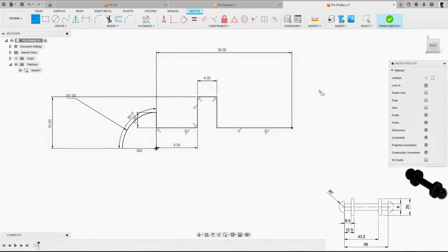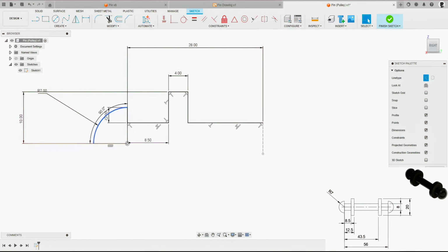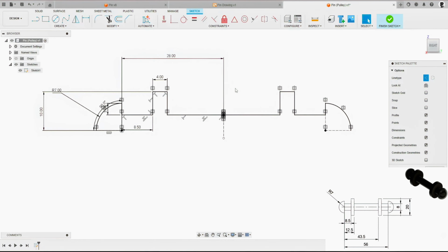Okay. Next, I'm going to use the line tool. I'm drawing a construction line down. And so the idea here, I'm sure you recognize already, is to mirror this across. And then we'll draw in a line of revolution. And then we'll go and use the Revolve tool. Let's use the mirror tool. I'm going to select all of this, and use the mirror line, which is the construction line here, press OK.